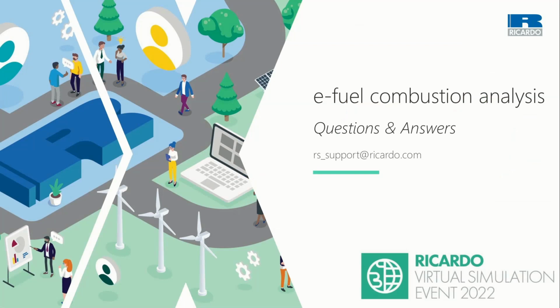In summary, detailed kinetics allow an accurate simulation of fuel composition effects such as differential evaporation on the cylinder mixing, combustion, and ultimately on the pollutant emissions. This stems from its ability to account for the numerous chemical formation pathways and incomplete combustion effects, themselves resulting from the fuel stratification and local composition changes arising from component volatility.